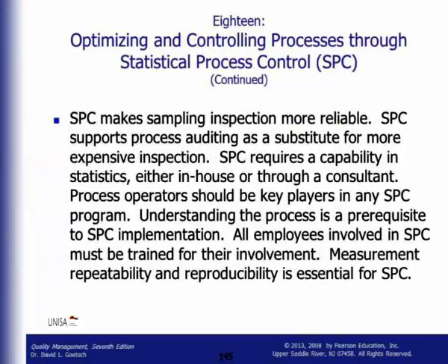SPC makes sampling inspection more reliable. SPC supports process auditing as a substitute for more expensive inspection. It requires a capability in statistics, either in-house or through a consultant. Process operators should be key players in any SPC program. Understanding the process is a prerequisite to SPC implementation. All employees involved in SPC must be trained for their involvement. Measurement repeatability and reproducibility is essential for SPC.